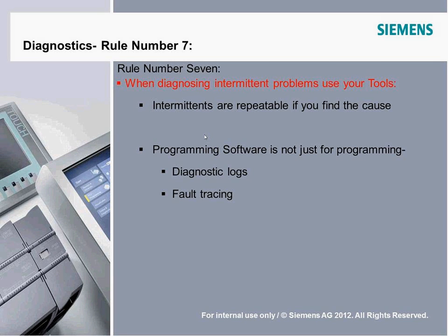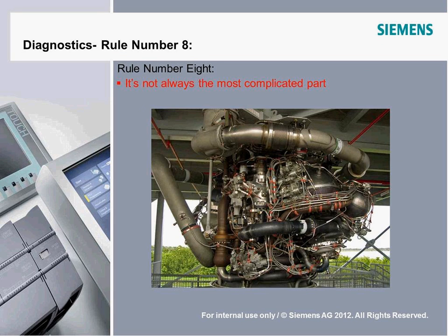But in any case, that was an example where the technical guy that had tried to fix that originally went out there and replaced an output module. He zeroed in on the analog output module that was controlling the speed of the pump, and he saw that it wasn't giving an output, so he replaced it. In this case, the do no harm rule was not being followed, because he replaced it with a different kind of module. Rather than a 0 to 10 volt output, the module he put in there was a 4 to 20 milliamp output.